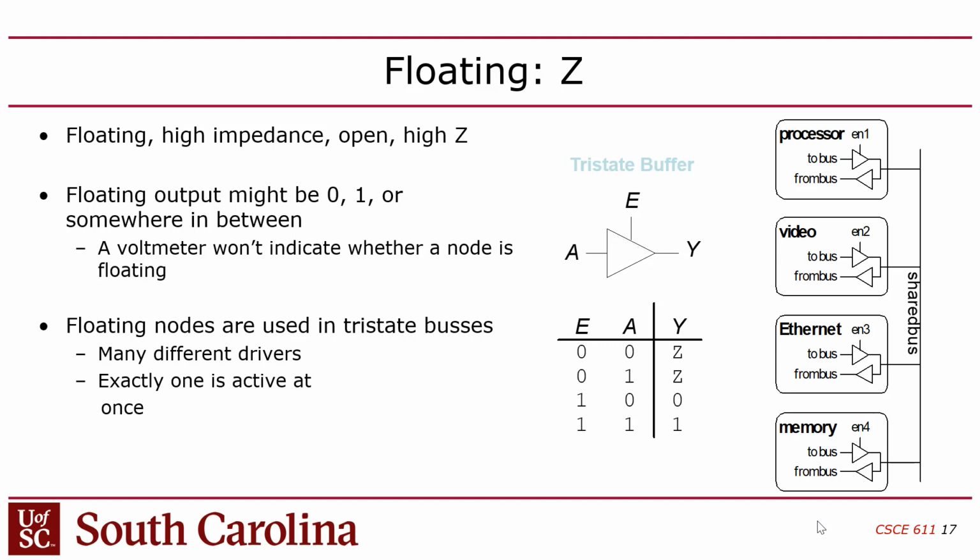There are limitations though, because in Verilator there's only 2-state logic. So you don't get the contention and you don't get the high impedance, right? Which is why we don't use it in this class, because Verilator is not a great way to do debugging and test because you don't get those 2 extra logic values, right? And I think they do that to make it faster. I think Icarus Verilog may also have the same limitation, but we never got to even try it because it doesn't even support SystemVerilog.